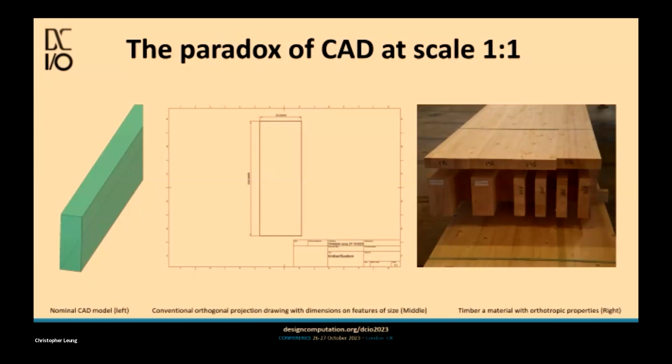But you have to recognize that real materials, actual substances, and the processes that put things together, whether it's joining, fastening, or fixing them into pre-assembled modules, they all either exhibit or impart variability in dimensional size and or tolerance and geometric form. And this is really one of the threads to pick up, that a way to do that is to use model-based definitions, which is the digital representation of manufacturing requirements.